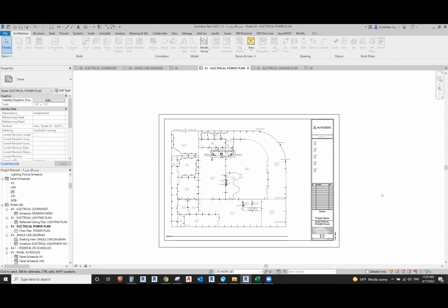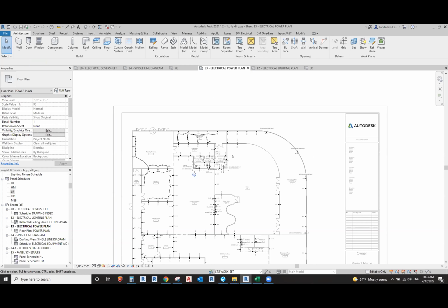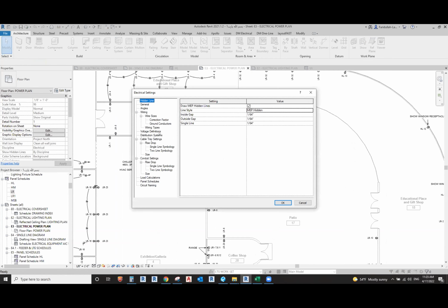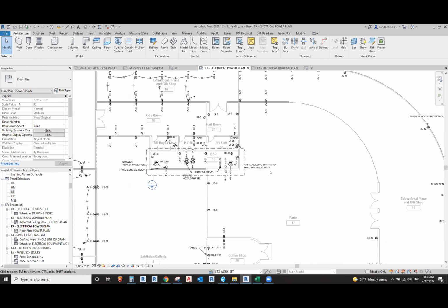For the configuration you mentioned in the report, it's all delta connection, right? You have access to this project, right? If you have the relevant one, you hit ES, go to the distribution system or voltage definition. So you can see what's the delta or what's the star connection, and what voltage we selected.